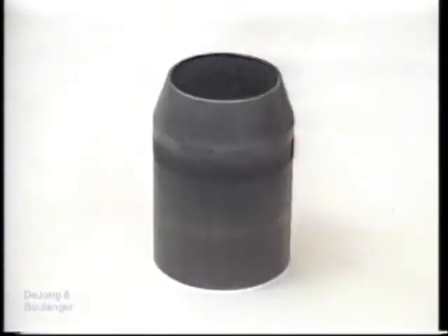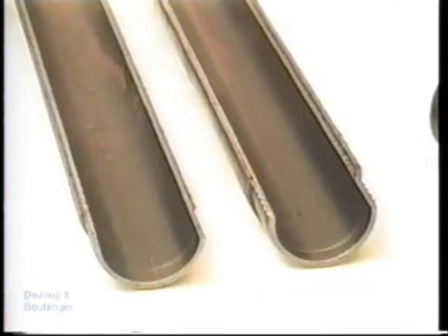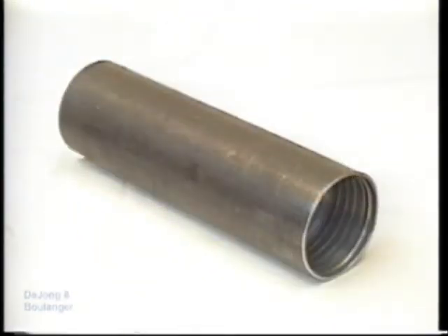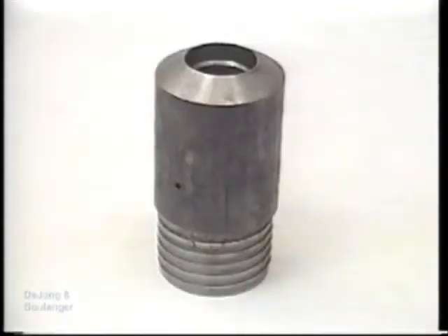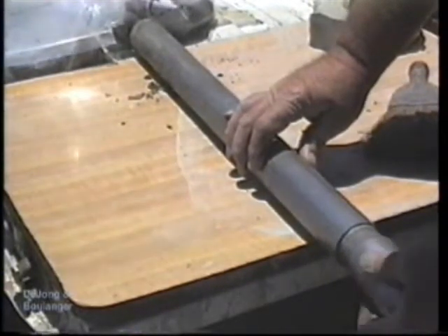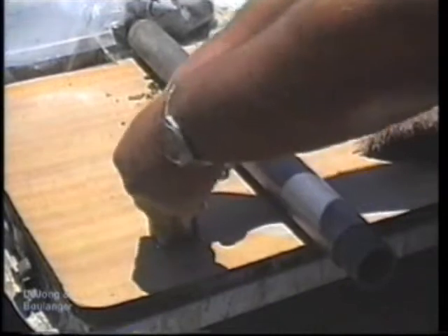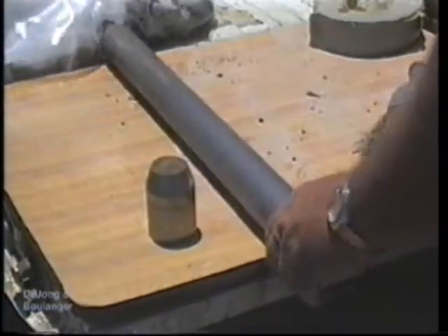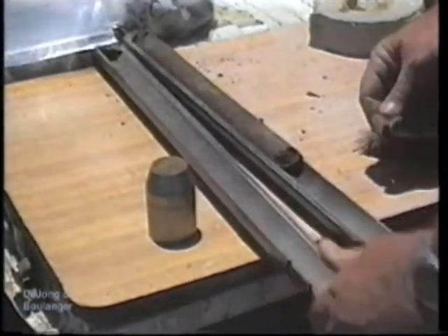Disturbed samples are generally used for identification tests including visual classification, water content, grain size, and Atterberg limits. The split spoon consists of a barrel shoe, a split barrel or tube, a solid sleeve, and a sampler head. When the sharpened, hardened steel shoe and solid steel sleeve are unscrewed, the two halves of the split spoon may be separated and the sample easily removed.